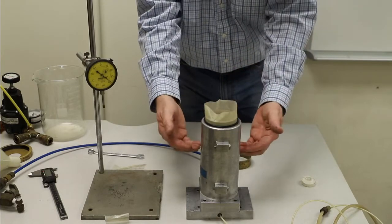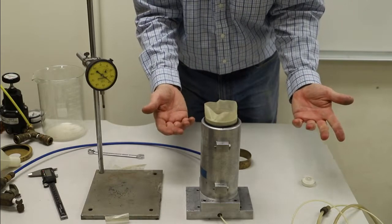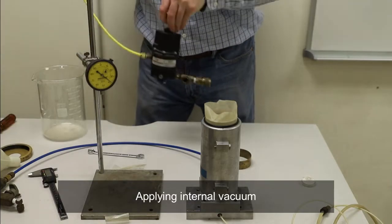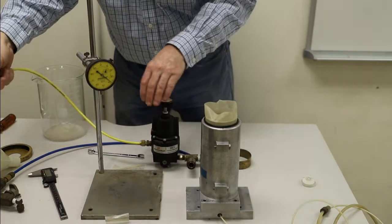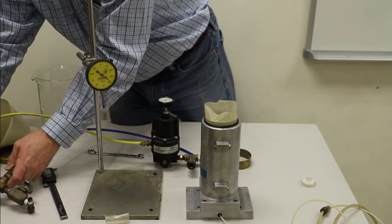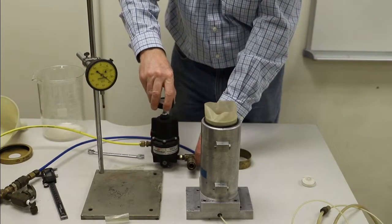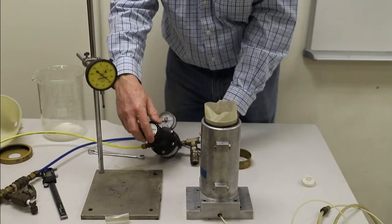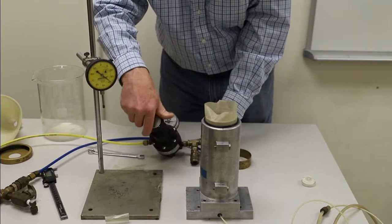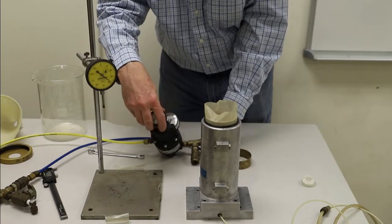We still have vacuum on the mold holding the sample to be round. We still have no vacuum on the inside of the specimen. So what we're going to do is bring over a vacuum regulator. And I'm going to plug that into the vacuum source as well. And this is like a pressure regulator, except it works sort of in the other direction, right? So I can set on this regulator what vacuum I want to have.